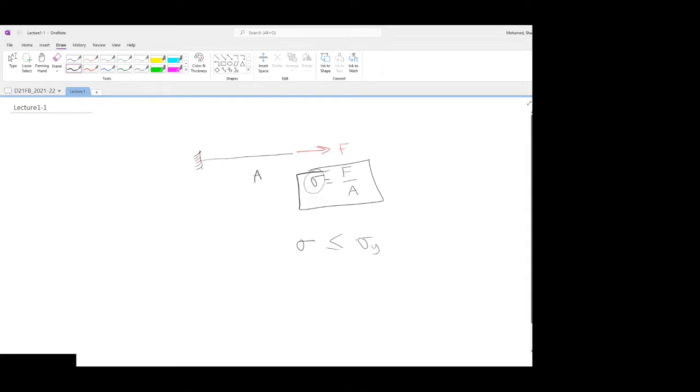I'm assuming that this is going to be steel, and you apply some safety factor. I'm going to put the safety factor in there. Usually you don't use sigma y, you would use some scaled down version of sigma y. In any case, you should not exceed this number, because if you exceed the number, the beam is going to fail. This is what you do. You agree with that? Okay.